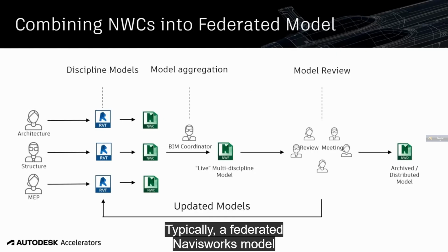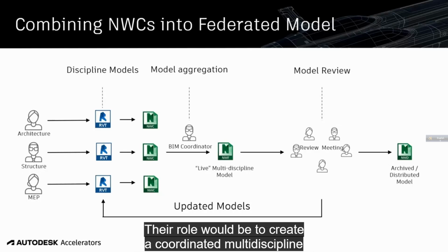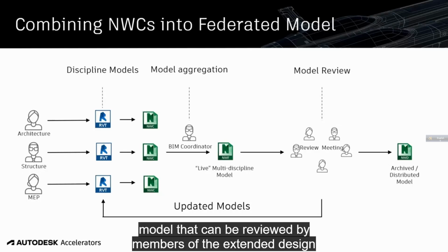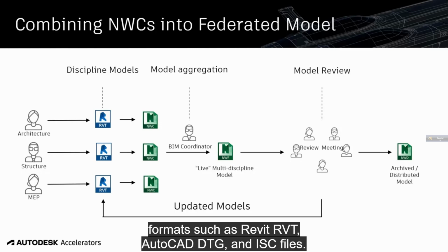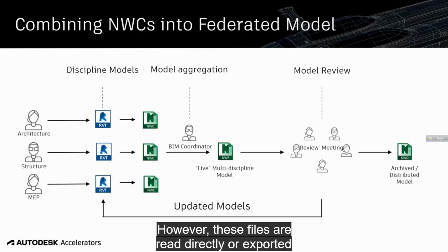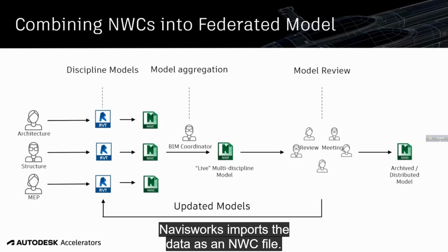Typically, a federated Navisworks model is created by a BIM coordinator. Their role will be to create a coordinated multidiscipline model that can be reviewed by members of the extended design team, subcontractors, or client representatives. As previously mentioned, the design models can be a combination of different file formats such as Revit RVT, AutoCAD DWG, and IFC files. Whether these files are read in directly or exported from the design applications, Navisworks imports the data as an NWC file. This stands for Navisworks Cache.